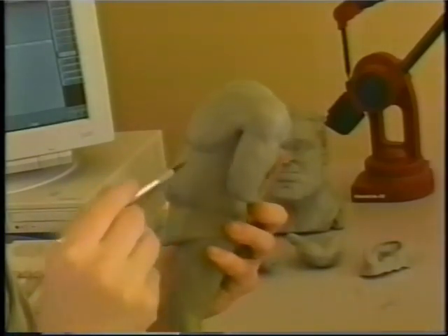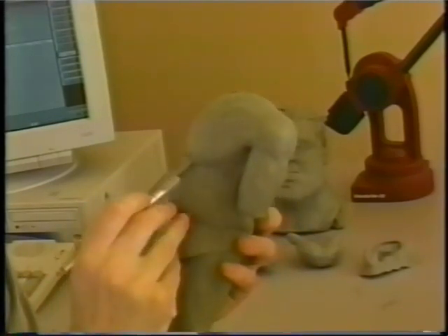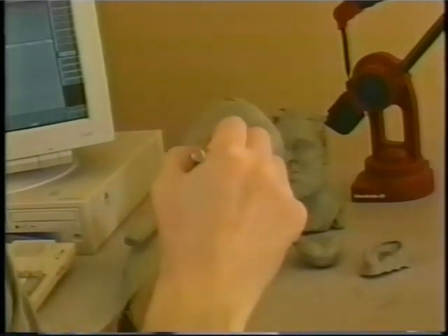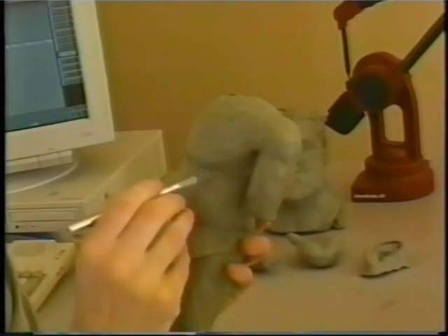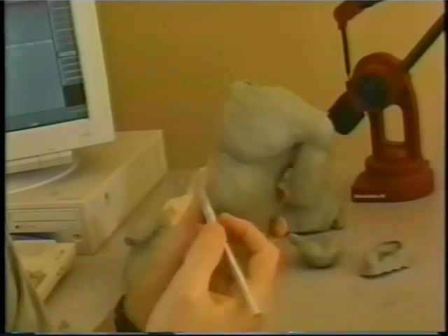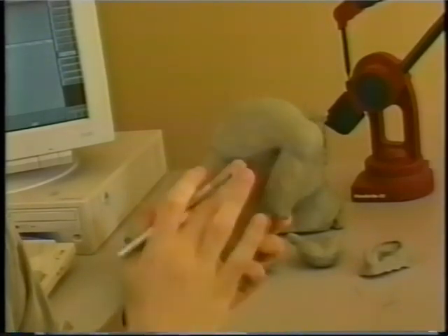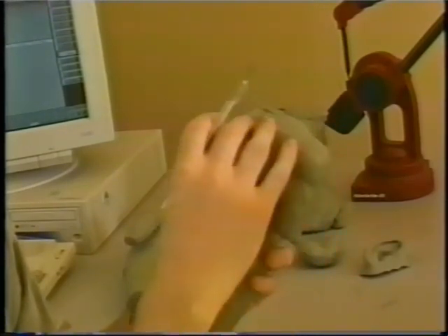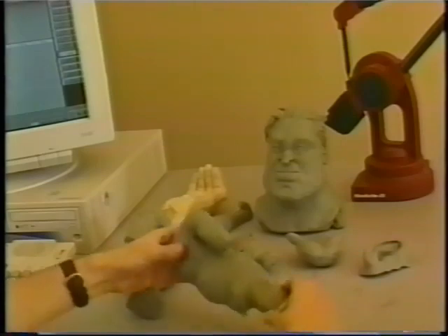Alright, but we don't have to do that. One thing you can do, and this is what I did in this case, is even though this is going a different direction, I matched up the number of points here going this way with going that way, and then I connected, if it were B-splines, the overlapping points here, or if NURBS, I could just use a transparency map on the edges, and by magneting these points together I could get this seamless look all along here, and so I could have this very complex situation where I had an arm coming off her chest and coming down this direction. That's one trick you can do. We'll look at that in the computer in a few minutes.